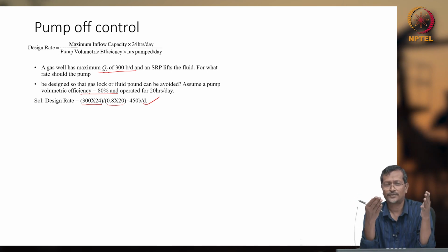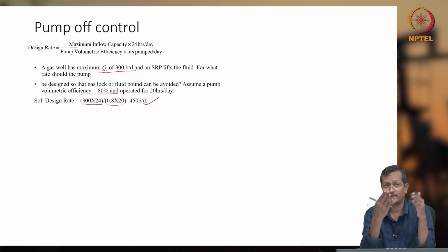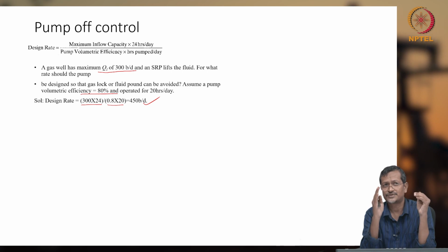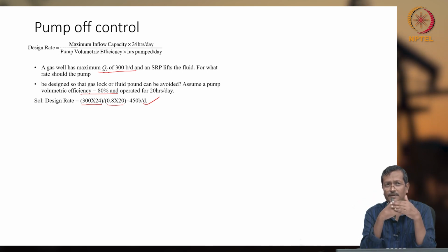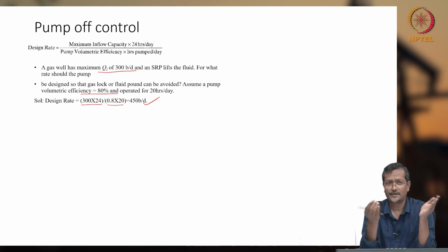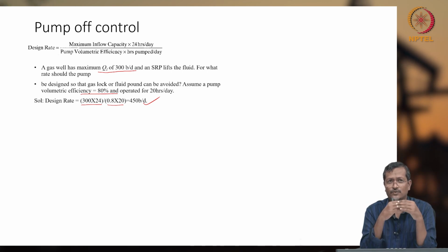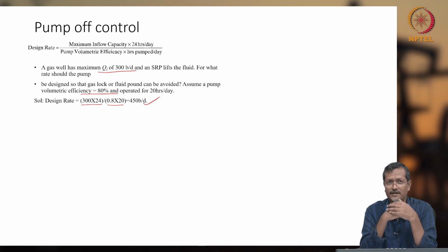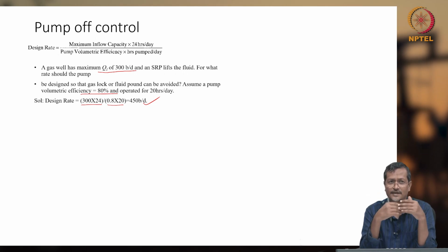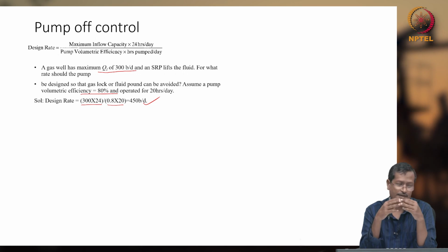Then how to know that your pump is getting filled by gas, 80% volumetric efficiency, 70%? So you have to study your pump curve or dynamometer curve. Using that, you can guess how much volume of gas is there, if there is any problem in the wellbore. So using that analysis you can do it. In the next lecture, we can analyze that.